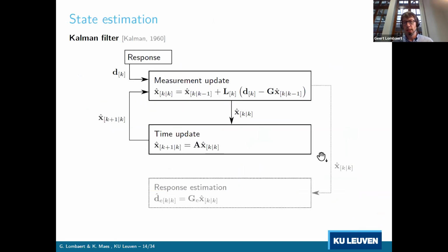This is done by a Kalman filter. Very, very briefly, what you have is some initial estimate of the state. You see how that initial estimate links up with the data. Based on this discrepancy, you correct the initial estimate to arrive at a final estimate. This combination is done in a way that takes into account measurement as well as process uncertainty. Then once this estimate has been made, it's moved forward in time and the process is repeated.